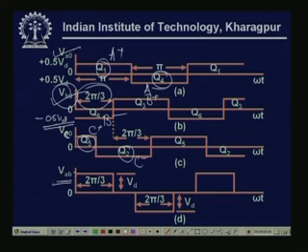So this is full Vd. On the other hand, what happens at this point? At this point they are the same, this is 0.5, this is 0.5. Therefore this goes to 0, and next time it again goes to negative. So now the line voltage actually looks like this.